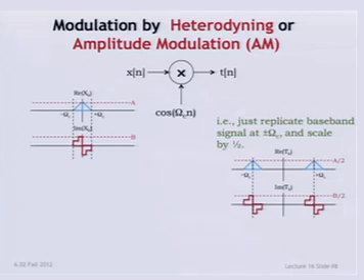So what happens when you modulate is you take the spectrum and you plonk it down on plus omega c and minus omega c, and you scale by a half. All right, so if the real part had amplitude a before, it now has amplitude a over 2, and the imaginary part similarly. I haven't drawn these to scale, but hopefully the labels are clear enough. Okay, so the modulation is that simple when you're thinking of what it does in the frequency domain.